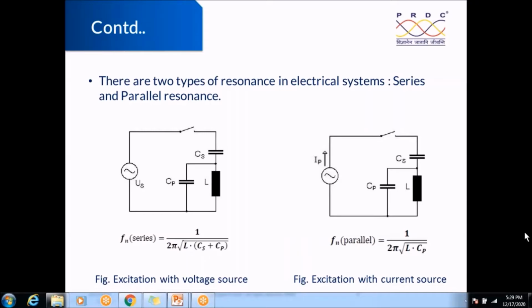Basically the idea is to improve the system stability. You know, our tower design mostly causes single line-to-ground faults, not phase-to-phase faults, because there is sufficient clearance between the phase conductors. So there is a very remote possibility of line-to-line faults or maybe triple faults, but the most common faults are phase-to-ground faults, and those faults can be temporary in nature. So we don't want to trip the entire circuit in case of a single phase to ground fault.